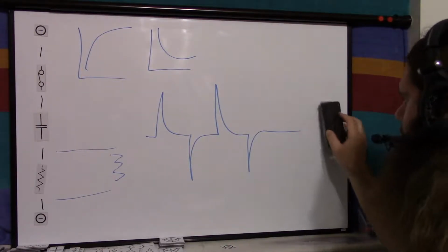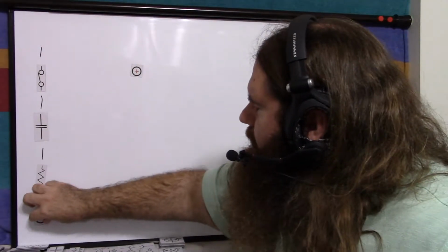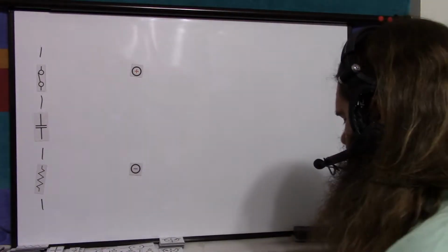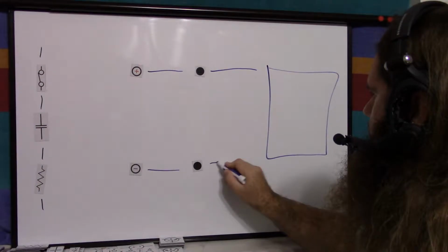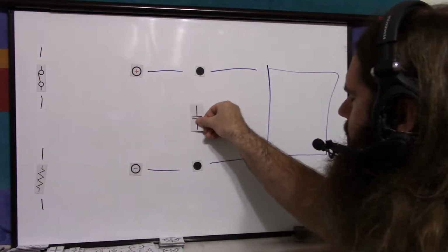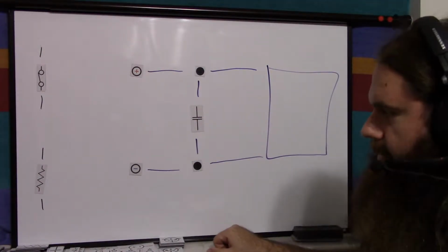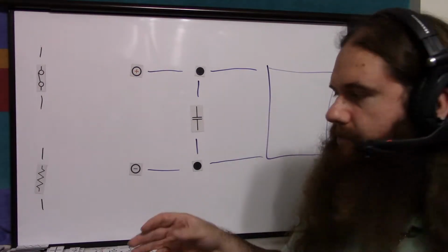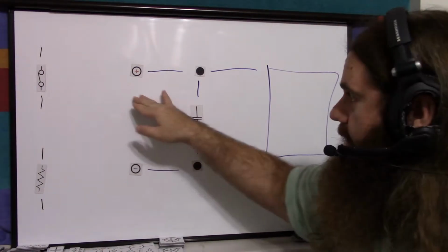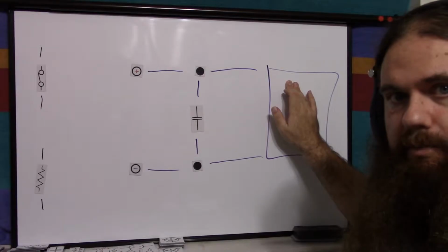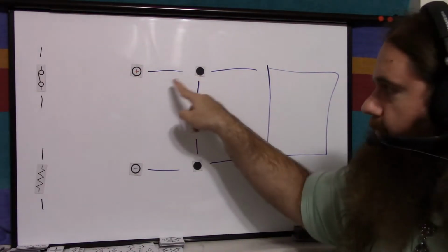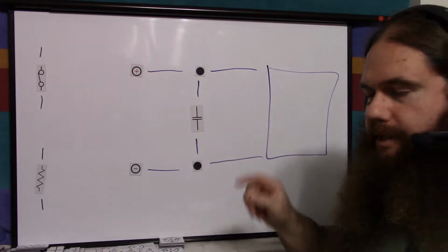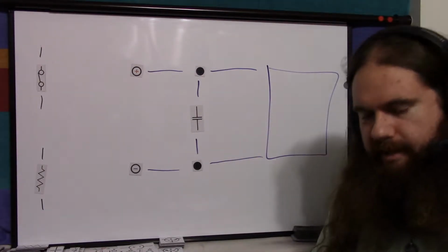Now, remember your bypass capacitor, where you have, let's say, your positive rail and your negative rail and your chip, your microchip, or whatever. So it takes a positive, it takes a negative, but then you have one of these. Now there's going to be resistance, otherwise you have a short circuit and your system is fried. There could be resistance coming in here. There's certainly resistance in the chip, for it's doing whatever it's doing, there's a load there. That's the point of the chip, right? Wherever the resistor is, this is essentially a low-pass filter.